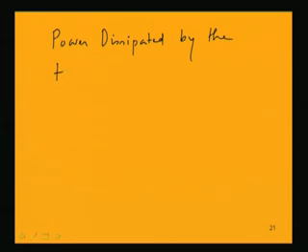So, what is the power dissipated by the transistor? If we find out the power dissipated by the transistor, by subtracting the output power from the input power, we get the total power loss, and from that power loss if we subtract the power absorbed by the RC value, that is IC square RC, then we get the power dissipated by the transistor as heat.